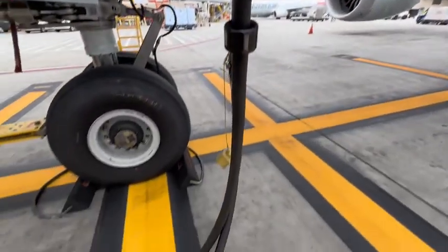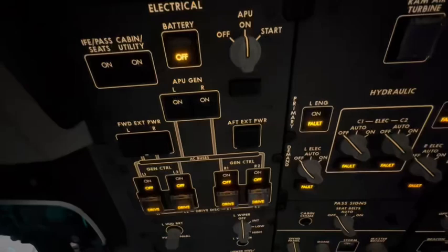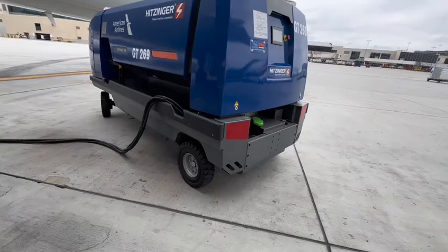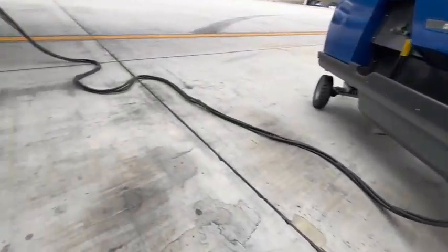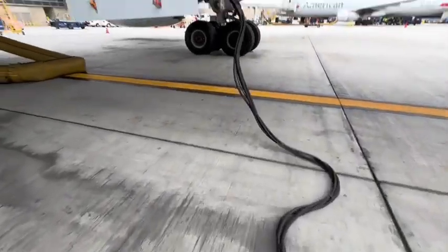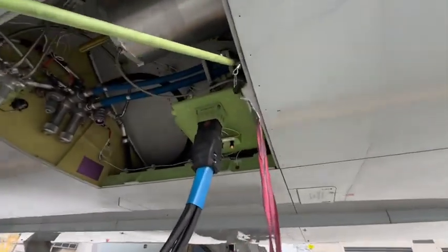Well, to answer that question, you're gonna have to look at the buttons down below. As I mentioned before, this aircraft is an incredible power hog. Not only do its internal systems require a lot of power, but also the engines require a lot of power. Why? Because the engines start on electrical power. Each engine has 2 generators. To be more specific, electric generators called VFSGs, variable frequency starter generators. To get enough power to start those engines, you're gonna need that 3rd power card. I mean, you can do it with 2 power ports, but the airplane is going to be struggling. This is why it's recommended to have that 3rd power card to get an engine running.